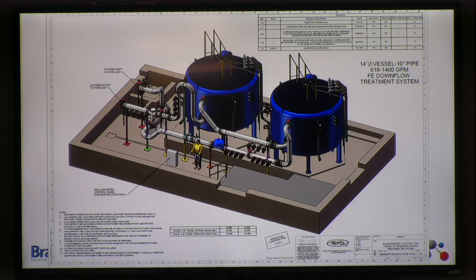I had a question after yesterday, we were talking about that. Is there a reason why people want to put that after well 6? Yeah, that's a great idea. We considered those options. You know, why not engage this closer to the treatment plant? And I think the idea was, you want to put this nearest the baddest water, the worst water quality, so that you can get the most efficient use out of the process. Right?